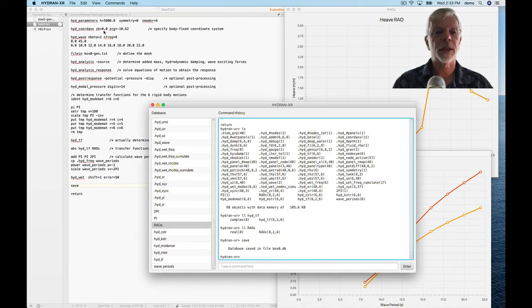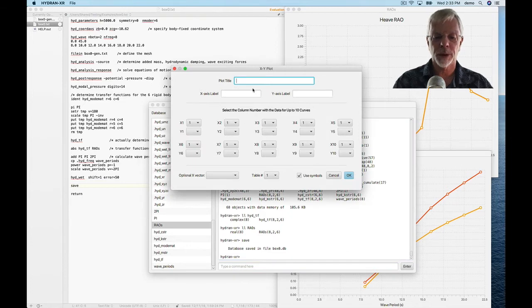And let's plot sway as well. So let's do here sway RAO. Really, we don't need to put this in, if we're just doing some simple checking, but I'll do it here, meters per meter. By the way, if we were doing roll or pitch, we would have degrees per meter because we converted to degrees, right? So 1, 2, let's see, we're doing sway, that's 2.